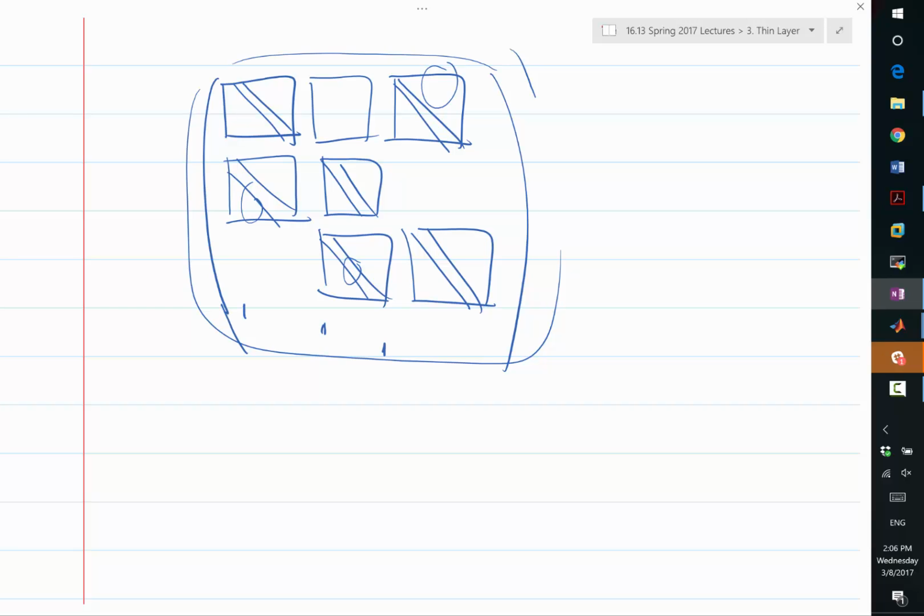I'm going to be integrating my u along the y-axis to give the outside what is my delta. That is going to be one off-diagonal term. And another off-diagonal term is going to be this entry, which in this case corresponds to the equation that my f prime at infinity minus 1 equal to 0. Now it's no longer minus 1 equal to 0. It's minus something that is provided by the outside flow field has to equal to 0. So that corresponding row needs to have another non-zero somewhere, right? Does that make sense?